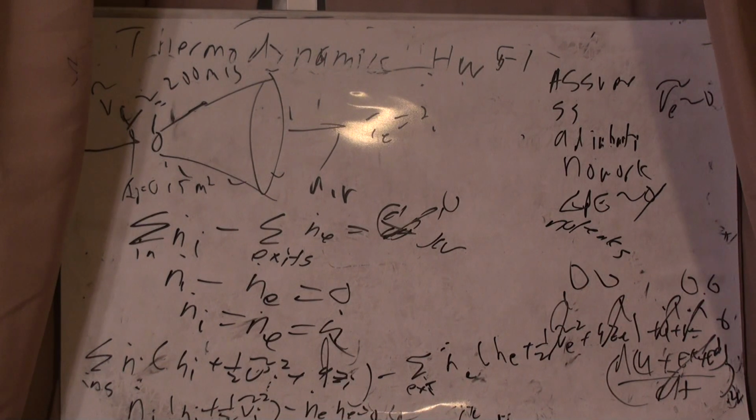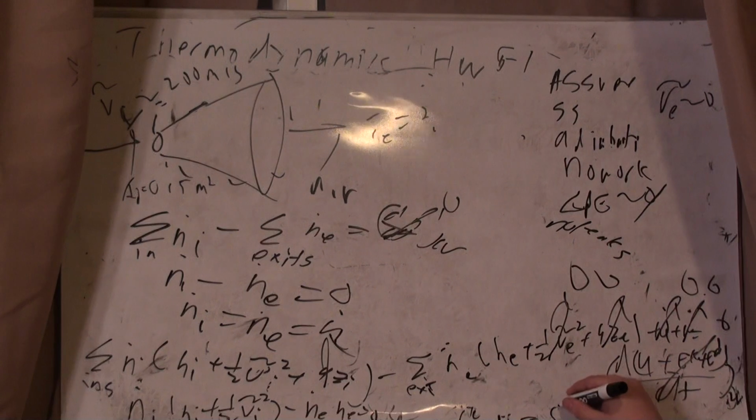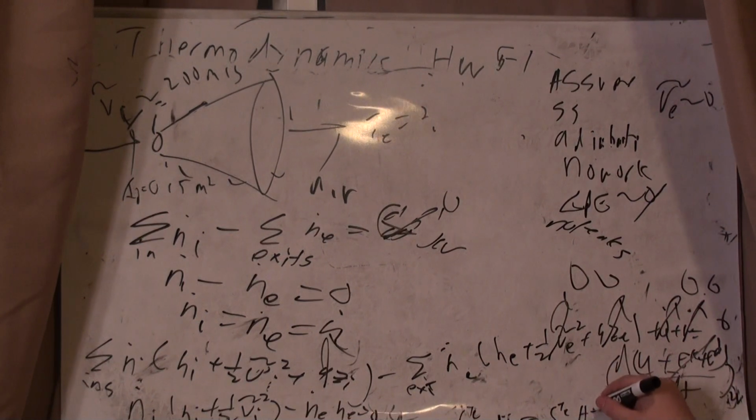Does it say anything else? No, it does not. So I do need to have the heat capacity, and so I go into the back of the book and I get my A, B, and D. So this is going to equal the integral from T in to T exit of (A plus B T plus D over T squared) dT, because C and E are 0 for air.